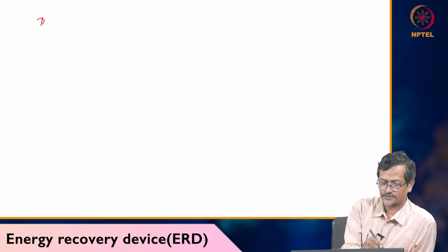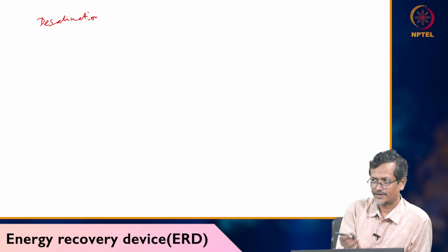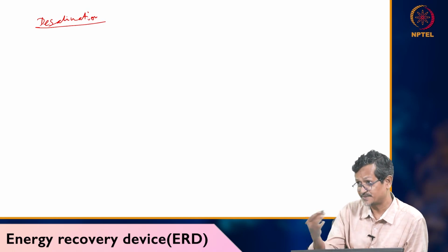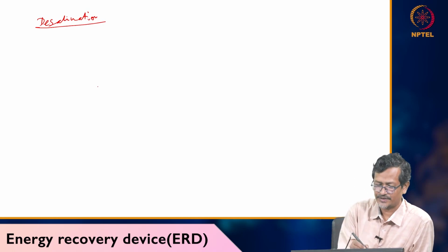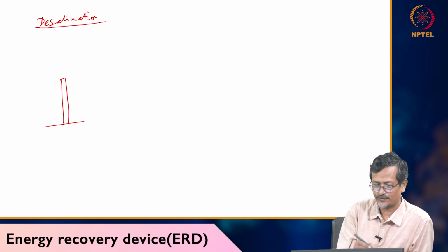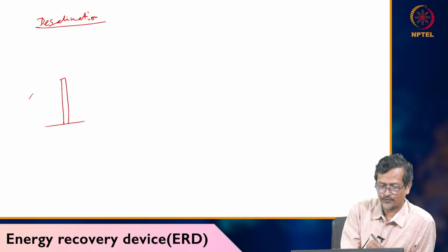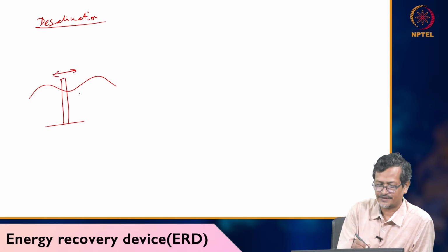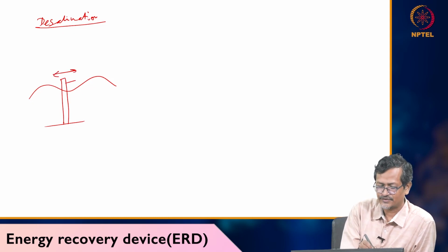Another work is desalination, we are working with the Department of Energy USA. So, our system was a wave energy based desalination. So, how did we arrive at the idea? We have a flat surge converter, a wave energy converter. When a wave passes over it, it will be moving forward and backward. With this forward backward motion, you can create a reciprocating pump here.